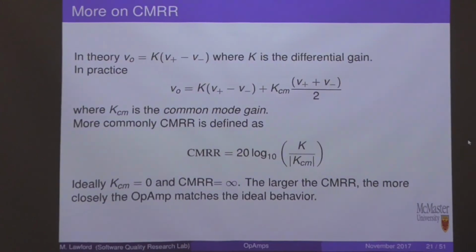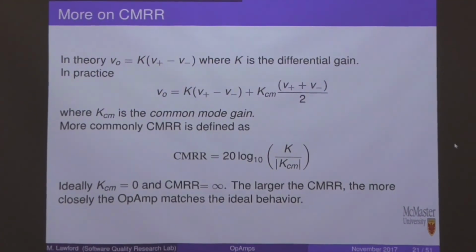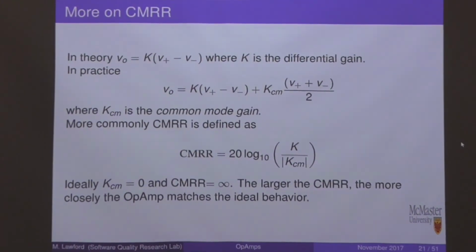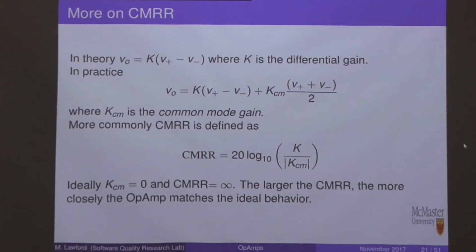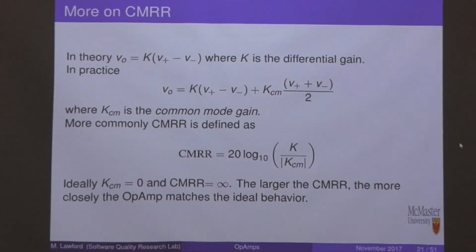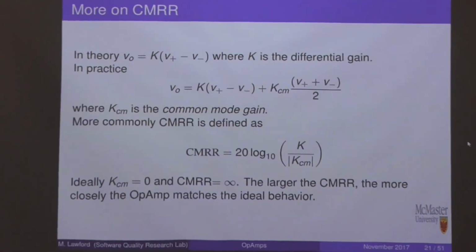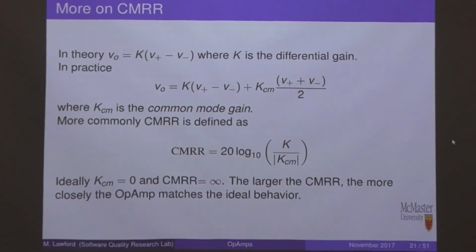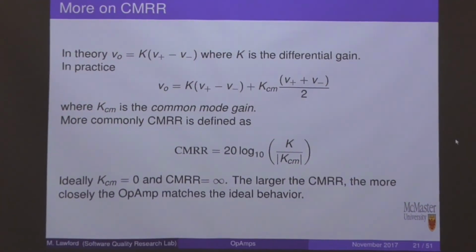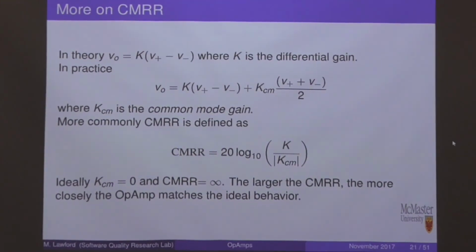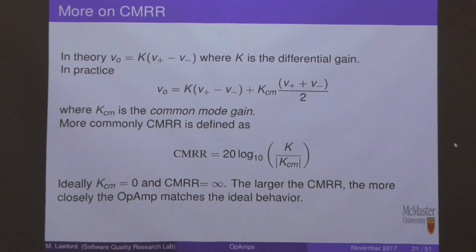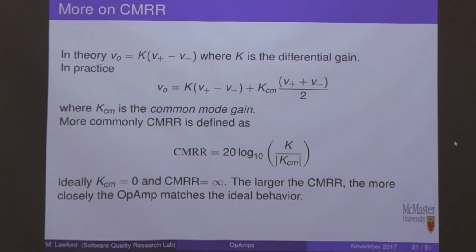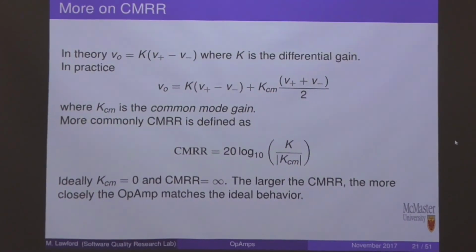Lots and lots of things are measured in decibels. Normally you include decibels as the unit. It's very frequent in signal processing. You'll see decibels because filters have the characteristic of rejecting frequencies with a certain amplitude. Generally speaking, with a filter, the point at which the filter rejects a frequency at a rate of -3 decibels is considered the cutoff frequency of that filter. Anything beyond that is considered to be too weak to be considered.